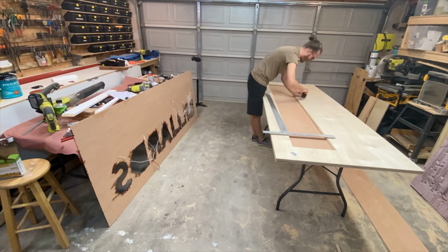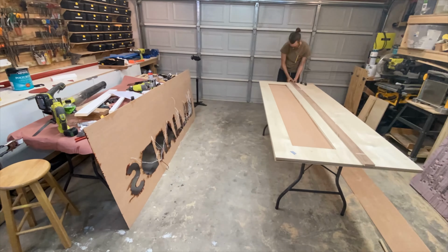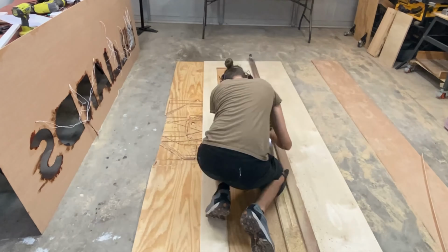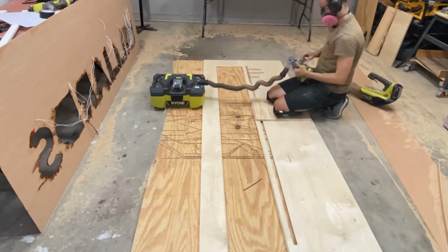Next, I need to cut some grooves for the wires from my LEDs to recess into. I measured my front panel with the wires and transferred those lines to the 3/4-inch sheet of plywood. Next, I used a 3/4-inch router bit and cut out the grooves. This is what the grooves look like after I cut them out, and here's the wires coming through them. This one right here is coming from underneath. I didn't want to cut that piece all the way apart, so it's just going to come out like that.